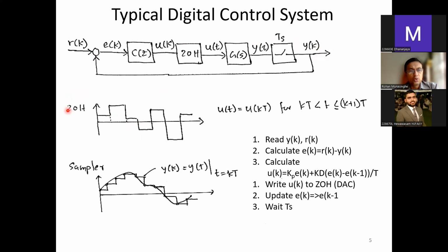See it over here, the zero order hold waveform. It holds the wave for one sampling interval like that. For the sampler over here, if y(t) changes like this, a continuous waveform, it takes the samples here, here, here, like that. It generates the samples. I have drawn it like a staircase together with the zero order hold, but in fact, if you don't have the zero order hold, it's just the samples, like this over here. I'll make this a little different in the text, without the zero order hold effect, only the samples.